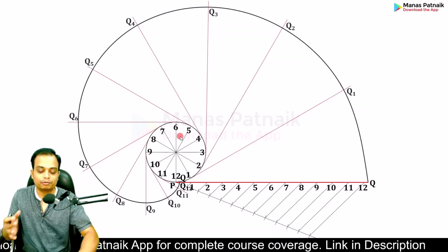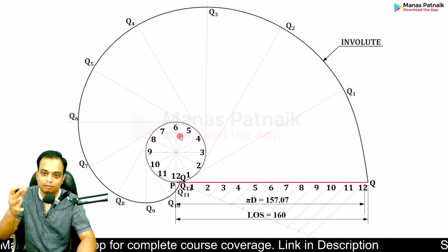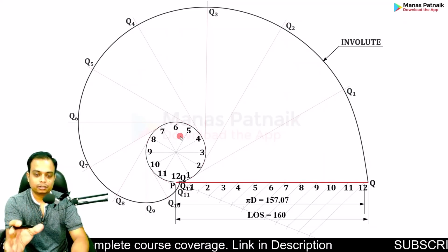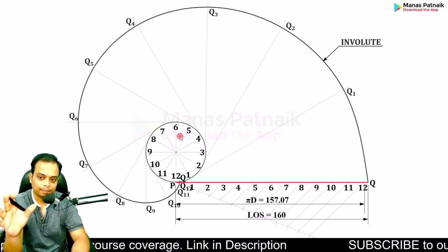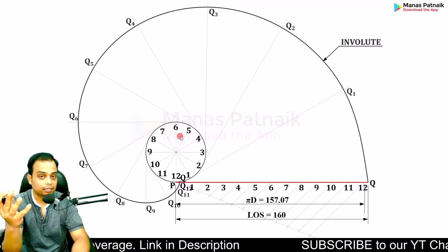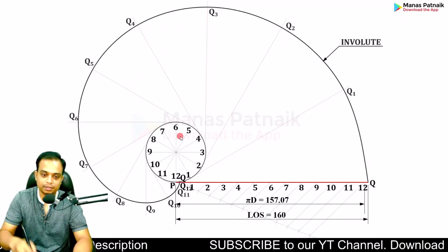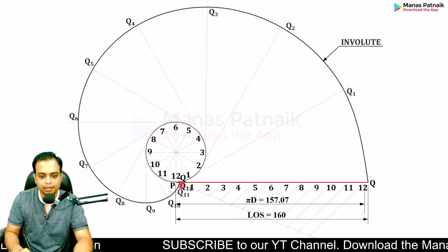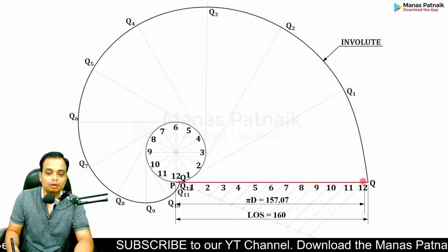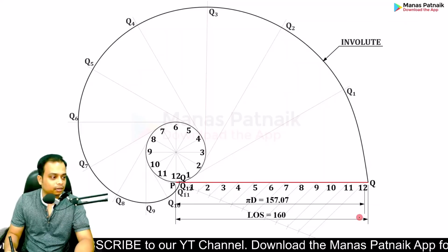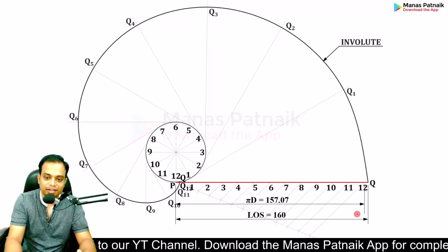It gives rise to a beautiful curve, popularly known as an involute, and this is how the construction should finally look. The involute, it's our objective, so it should be dark and thick. Okay, circular disc, keep it thick. The string, keep it thick, no problem, and then do the dimensioning as well. So in 9 minutes we have finished the problem.